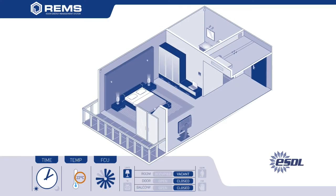In scenario 2, when the room is vacant of its guests, a default or an energy-saving setback temperature will be managed via the REMS software, for example 26 degrees Celsius. The lights and appliances are also switched off once the room is vacant, but will immediately return to the status the guest left them in upon their return. During the guest's absence from the room, the DND will indicate the room status to chambermaids or maintenance staff, assisting the efficiency of internal operations.